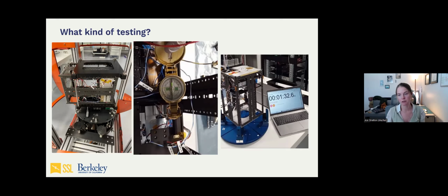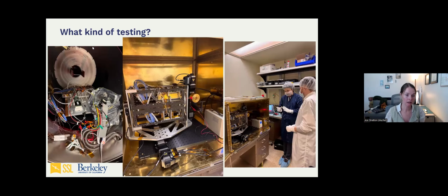Then, of course, we had to deploy systems. So here on the top is a UHF antenna. We had to tie it over and over and over with cute little fishing wire and a resistor, and we had to tell that resistor to get really hot until it melted the fishing wire and the antenna blew out and deployed. Because you really need your communication system to work in space. So we tested that.